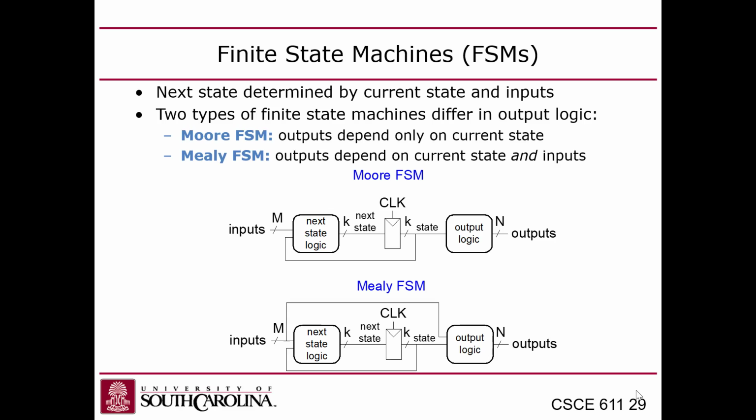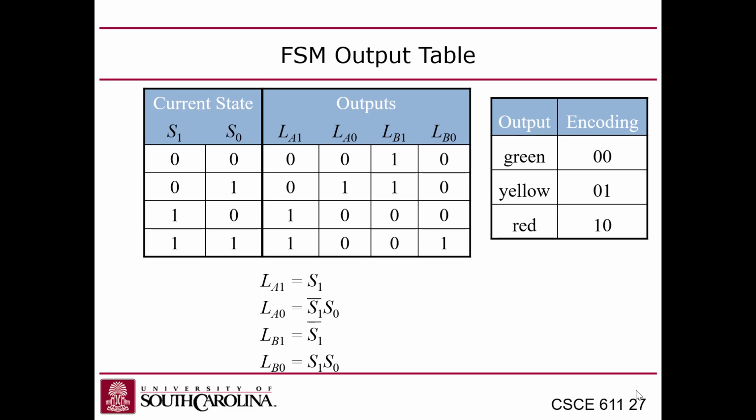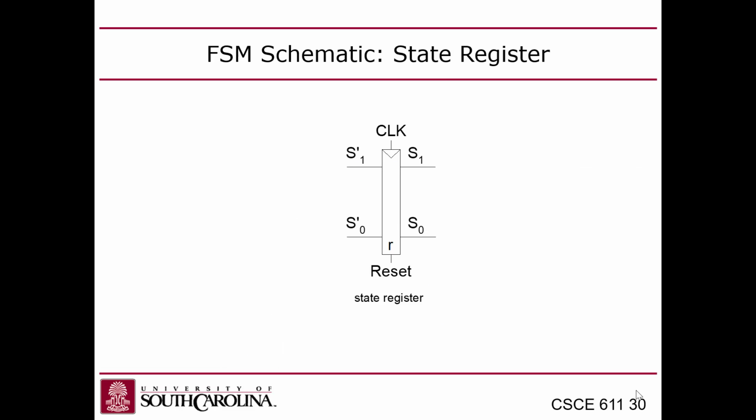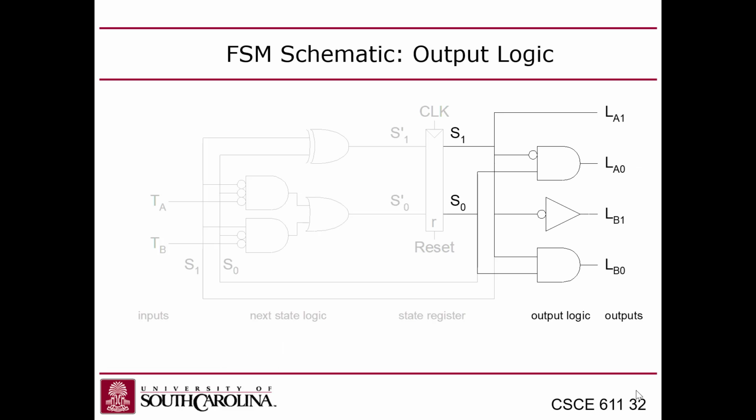Whereas bit 0 of the Academic Avenue light signal is not S1, S0. So not S1 is shown here with a bubble on this AND gate, and S0 is the second input on this AND gate. So there's bit 0, and the other ones are set up the same way. So that's the whole traffic light controller.